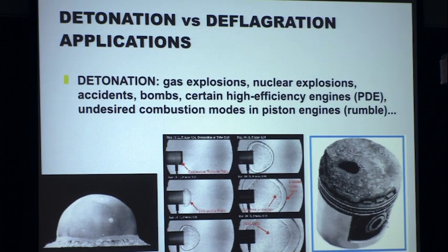This is what people call knocking. It's not knocking, it's super knocking, or rumble if you want. This is really something you don't want to have, and you have it in engines today. Certain engines go into this kind of detonation regime, and that's the end of the engine.